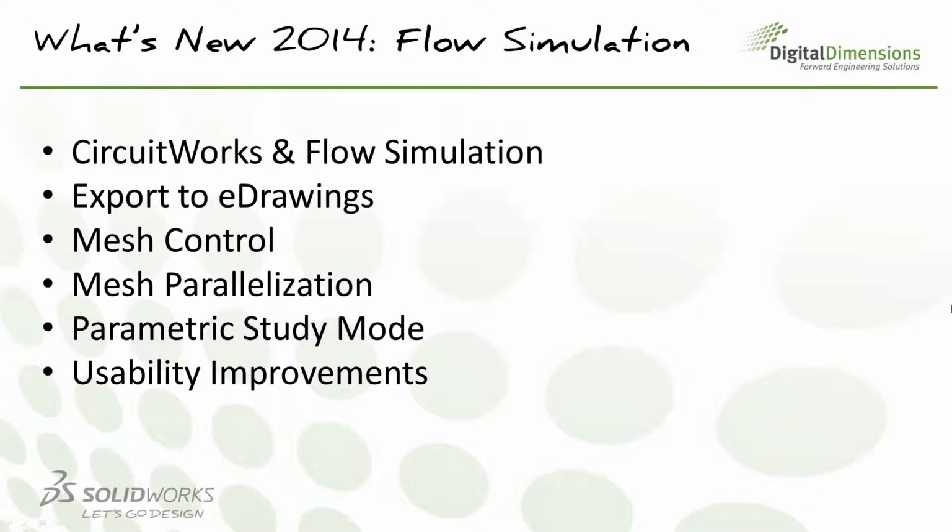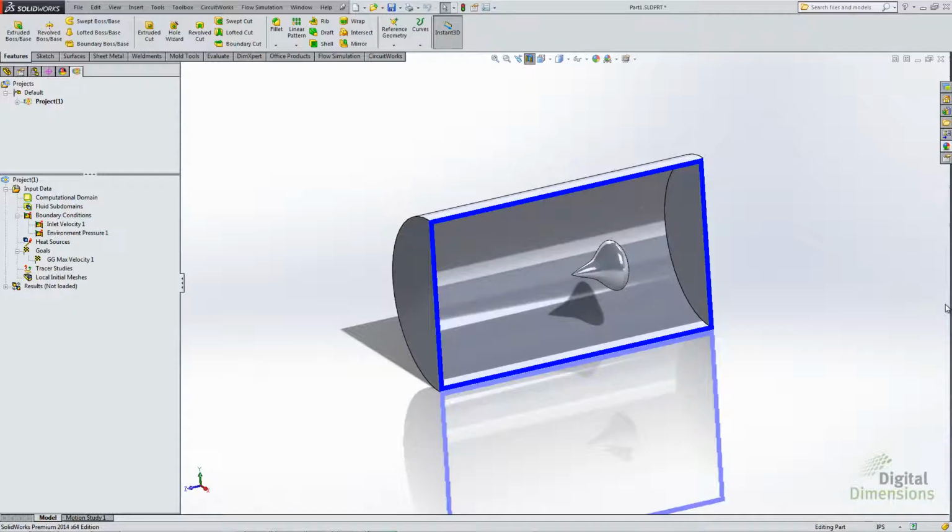Moving along, let's talk about parametric studies. Once we generate a new parametric study, whether it be an optimization or a what-if scenario, SolidWorks will automatically generate a new entry for your parametric study under your project. This improves flexibility with the tool. Instead of having to save and reopen our setup, that setup now exists within our project and can be accessed later on.